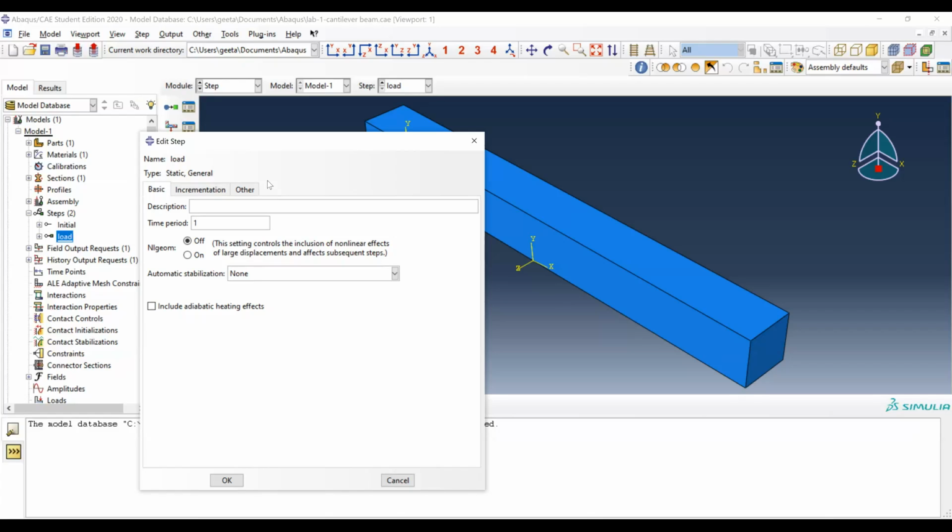Unless you are working with high strain rate, high stress rate or high loading rate conditions, which are very close to the minimum natural frequency calculated for your structure, you don't want to use dynamic analysis, because it's very computationally expensive compared to quasi-static analysis.